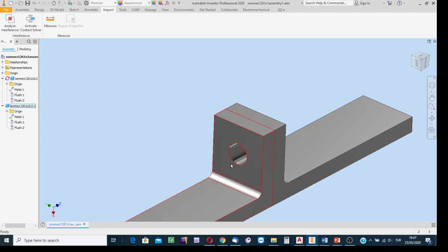This side there will be a washer. Its thickness is 3 millimeters, near to 3 millimeters. I said 8, 8, 16 plus 10, 26 plus 3, 29. One more 3, 32. Okay. And 3 more millimeters of further extension is a good practice at least.